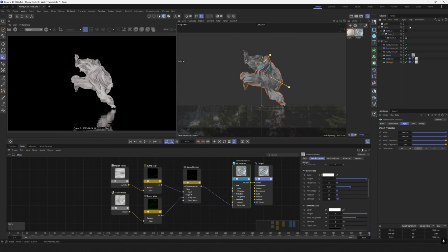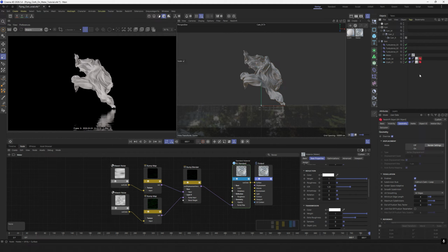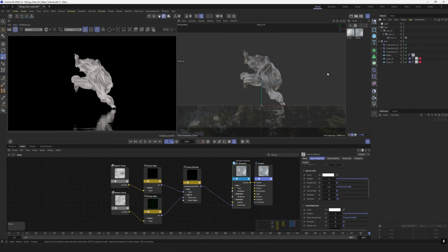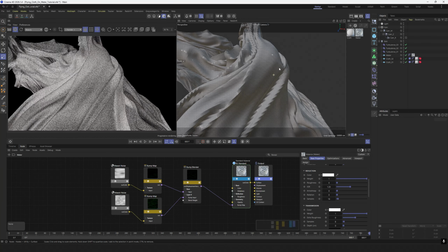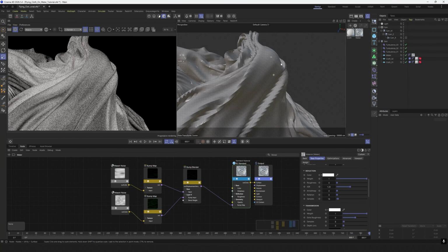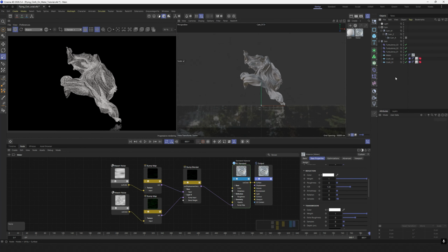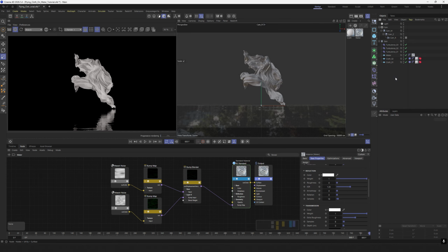Select the object, go to the text menu and select Render Text. Add a tag to the object. Go to the Geometry tab and activate Override. Activate Tessellation and duplicate this tag on the second plane. As you can see, everything is smoothed out and there is no more bending. Now let's move on to setting up the lighting.